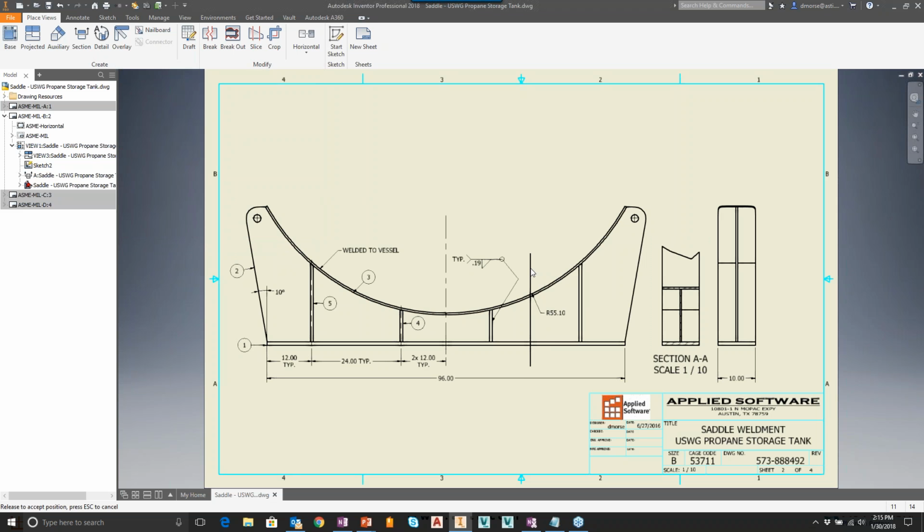The thing is that this section line can easily be moved by just clicking and dragging it. So an accidental move can happen as you're moving and clicking around. But in addition to that, if this view updates any, then updates to the view can actually cause the section to move around just slightly. So if we want to make sure that we have a precision section placement as well as keeping it from moving, we'll use these little tricks here in order to do so.